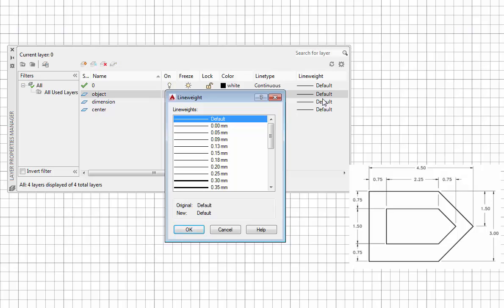If you're not familiar with it, you can go ahead and search alphabet of lines or look in your manuals for that information. It'll show you the hierarchy of lines, what lines take precedence, and then what lines are typically thicker and darker, like object lines, break lines, as opposed to thinner lines like hidden lines, section lines, those are typically a thinner drawn line. And so we can control the line weights with this.